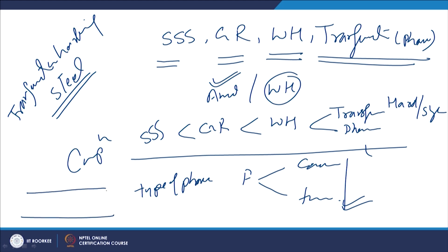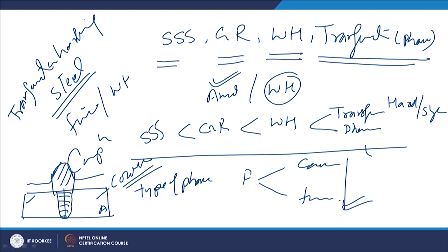Say, for example, if annealed steel is subjected to welding through the plastic deformation approach, it will have the work hardening effect in the weld zone, while in other regions there will be annealed base metal with minimum hardness and lower strength. So, if we plot the variation in hardness for the annealed steel, then in the weld zone it will offer greater hardness due to the work hardening effect as compared to the annealed zone. Obviously, the annealed base metal will have the coarse structure, while the plastically deformed or work hardened metal will have the fine grain structure as well as the work hardening effect.